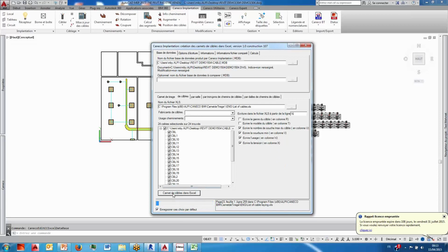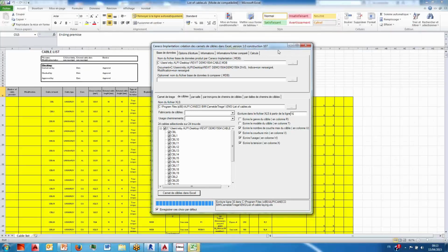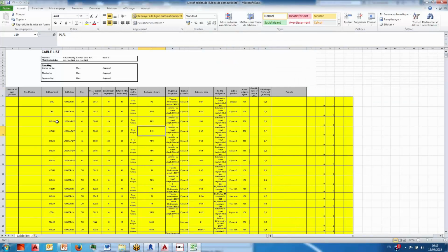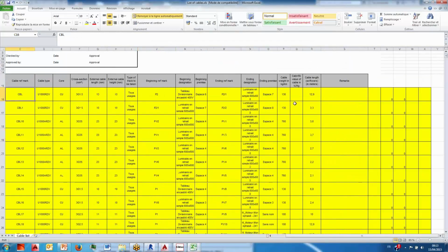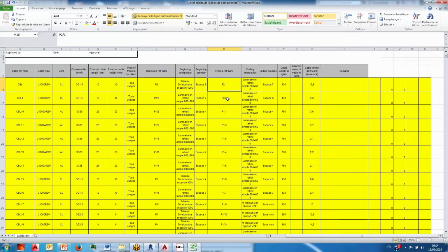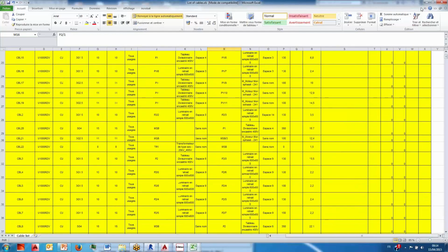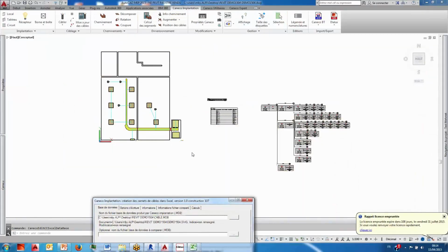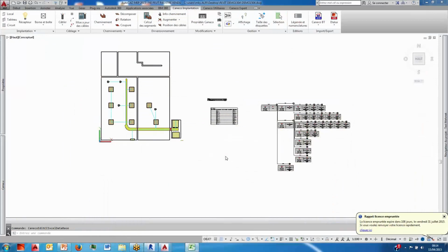This, we can of course do something with some less information. So you can generate a sample cable trace. This is a cable with details, a cable list with details, detailing all the cable and all the cable tray arrays. And we can also create a sample documentation, a cable list, just to where it's coming from, the beginning and the ending of the circuit. So that's what we can generate, the kind of documentation you can automatically generate after that you have defined.